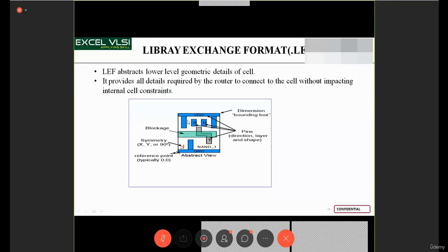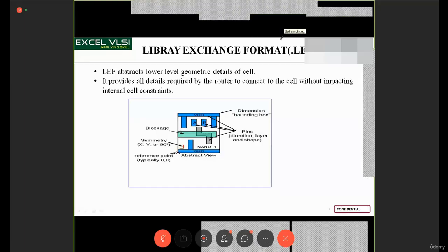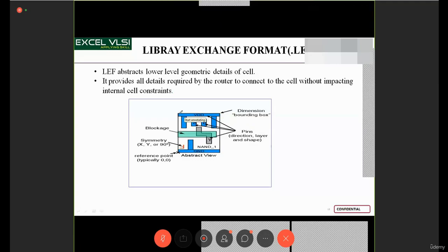So it is surrounded by a metal with a blue color implication. That is nothing but the physical attribute of that particular pin when you may want it to interconnect when you're doing the physical design flow. These are some blockages you can see, as I mentioned in the previous slide. For each cell, you will have height information. This is your cell height, or the unit tile information.